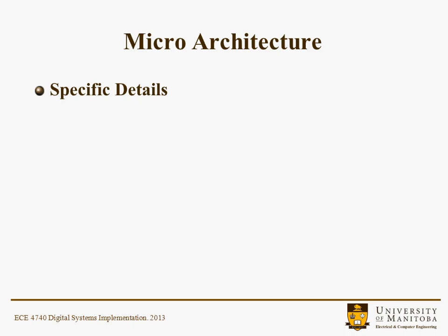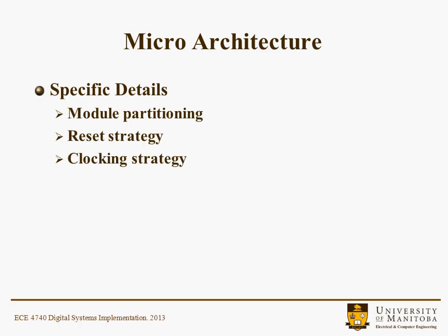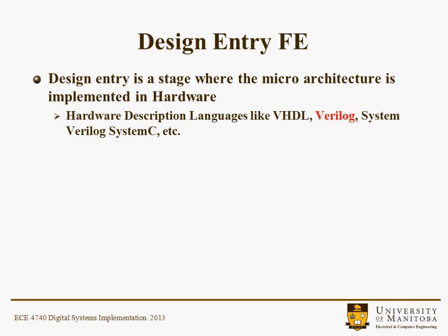Burrowing down a little bit further to the microarchitecture, some of the specific details, you have to partition your design. Of course, that's a very, very standard technique for design. It's basically making things more modular and smaller and easier to deal with. You'll need some type of reset strategy upon power up or reset. You have to put the machine into a known state. Some type of clocking strategy, verification strategy, testing strategy, and those things all have to come together to build your ASIC.